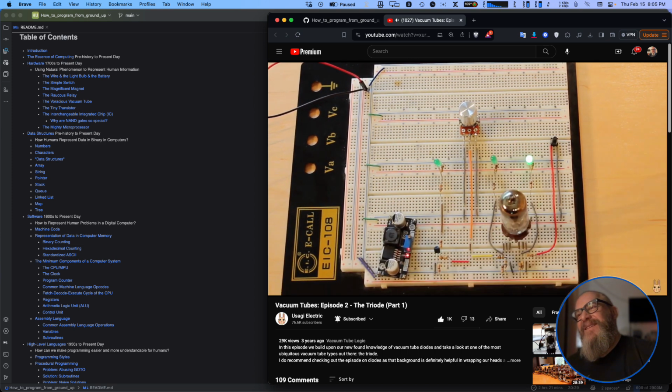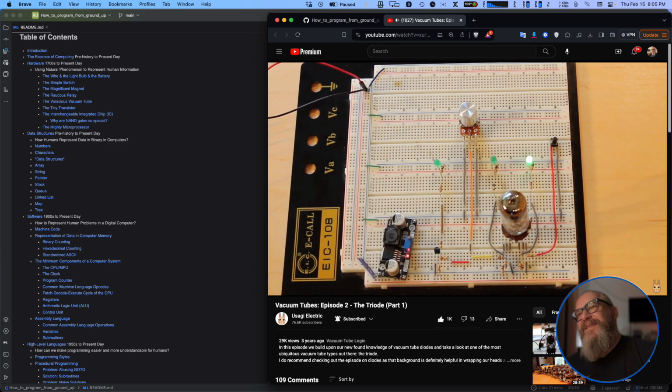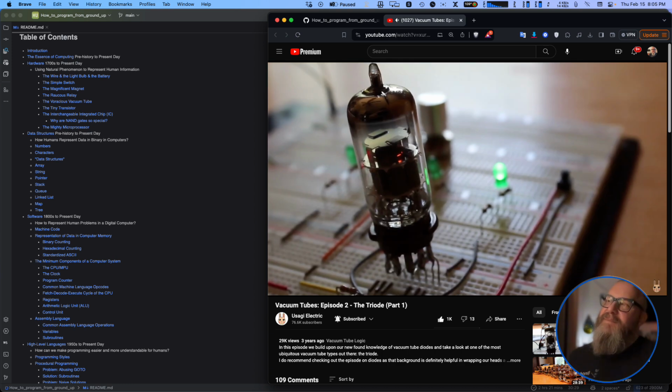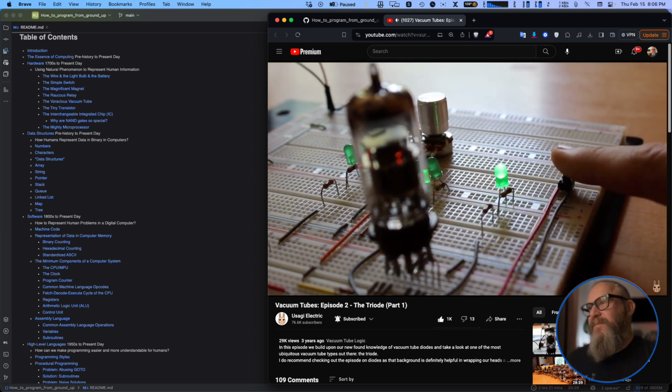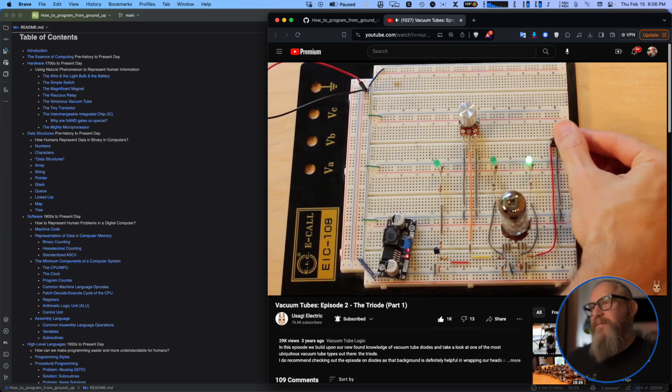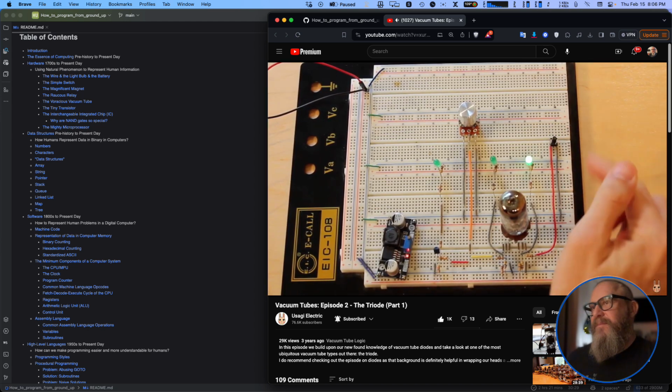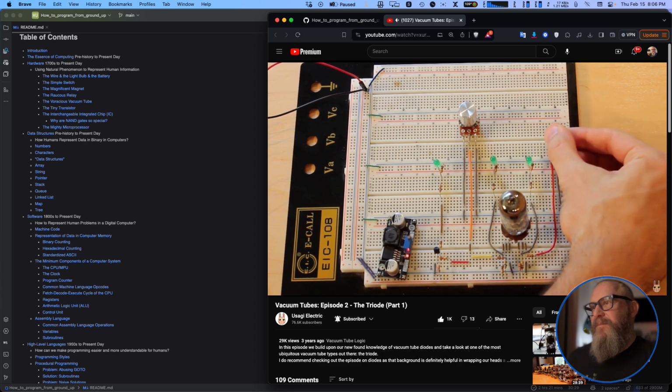What I really want to focus on right now is the button on the other side. You'll notice that our LED is on. You'll also notice that I have these voltage drop resistors in parallel to the LED. We'll talk about why I did that in a minute after we experiment with the actual vacuum tube. If I press that button, we should see that LED turn off, because when I push that button, we put a positive voltage into the grid, and that should pull our output low. Let's see what happens. Awesome, the LED turned off. That is amazing. So we have it functioning on and off like that. That's very cool. You can see I'm using just a 6-volt input to control our output here, and that's what I'm showing with the LED by pushing this button.